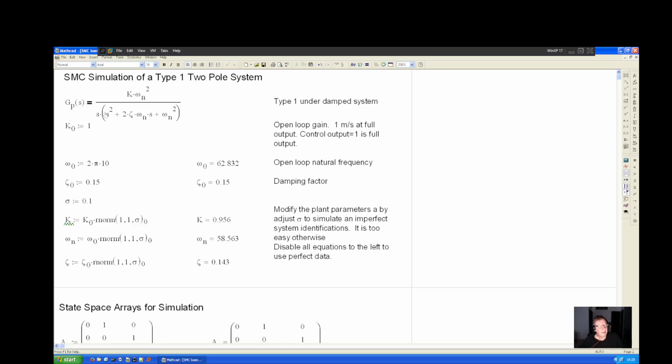This basically approximates a hydraulic system in velocity control, and then this integrates velocity into position. So what I have here is an underdamped system that represents kind of like a mass between two springs, which is the hydraulic volume on either side.